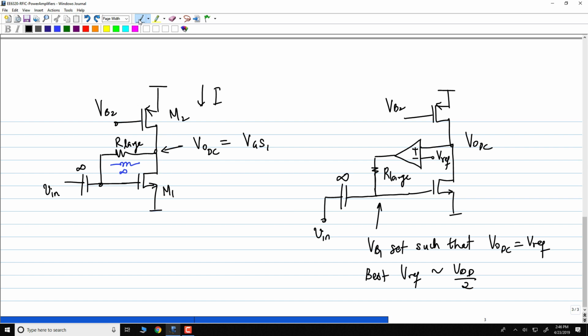Sure, you can do all of that. What happened next? What did you do next? You remember there was one more better modification of this circuit. What was that? What is the gain of this circuit at low frequencies? It is GM1 times R01 parallel R02, correct? If you have an RL like 50 ohms, it is not that much. It is only GM times RL. 50 ohms is too small. Go back to the analog circuit.